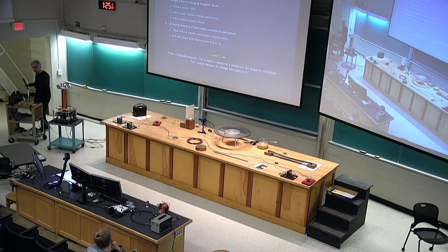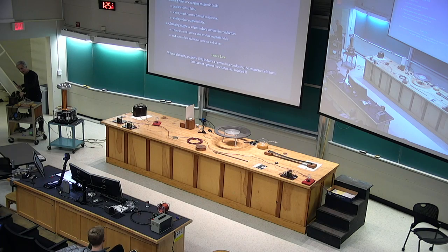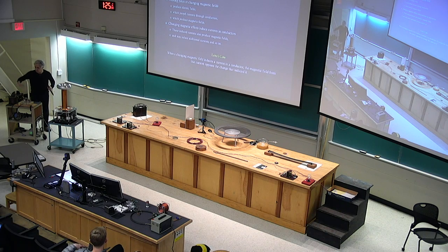When I turn this on, which I've just done, there's now current flowing in the coils. That by itself makes a magnetic field. It's moving charge, after all. The magnetic field we get from that is relatively weak, so it's not very fun to show you. Instead, we magnify that field by letting it magnetize a chunk of iron, this pole piece here, or this one. The two of them are both magnetized. Actually, they're magnetized in opposite directions because the coils together are reversed.